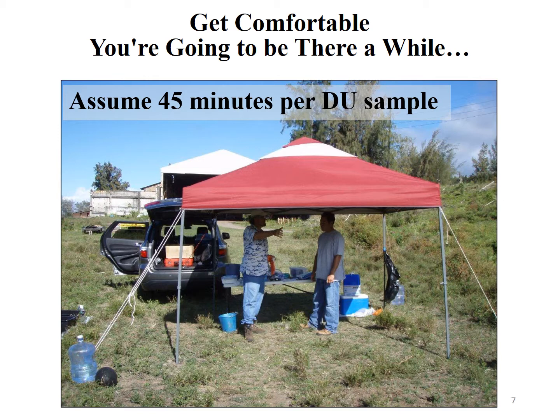Depth of soil collected in a surface soil DU is dependent on the investigation data quality objectives. This could be as shallow as 0 to 2 inches if the focus is on, say, what a child may currently be ingesting from soil exposure during play in their backyard, but more typically investigations of surface soils in Hawaii have targeted the 0 to 4 inch or 0 to 6 inch depth interval.